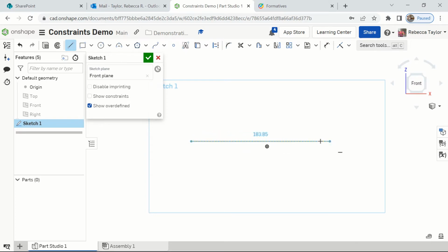So in Onshape, see where there's a little horizontally dashed thing. It's not there, it's there, it's not there. I'll do that a couple more times so you can see it. Not there, there, not there. That little dashed line is the automatic constraint. So we're dealing with these automatic constraints that these programs will put on there. Okay, so there's the first one, and when I hover over it, you can see the horizontal constraint.